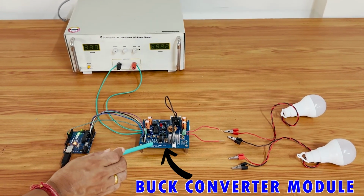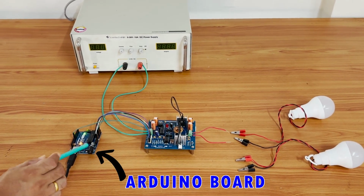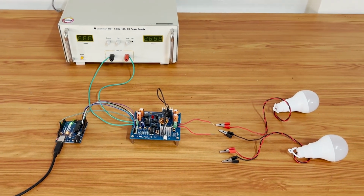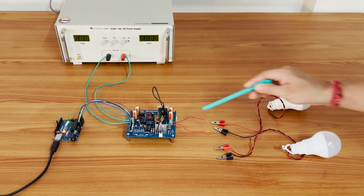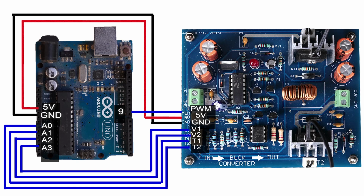We here have a buck converter module which is connected to Arduino board. The input to the buck converter is given from a regulated DC power supply. At the output side we have two LED lamps of 12 volts and 9 watts each. These lamps will be connected to the output terminal one at a time. Follow this connection diagram for Arduino and buck converter.